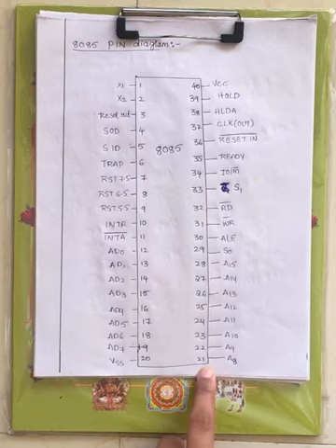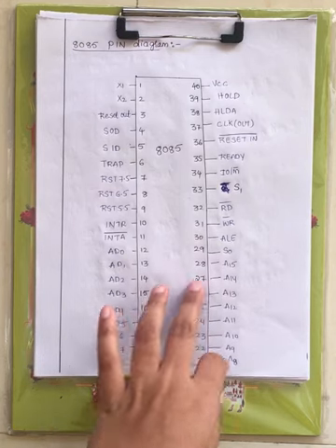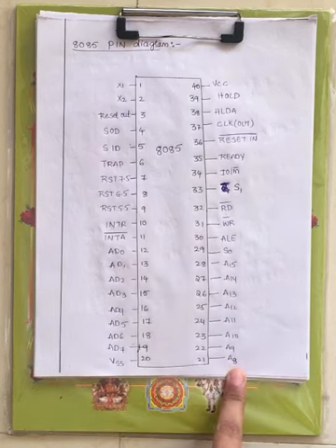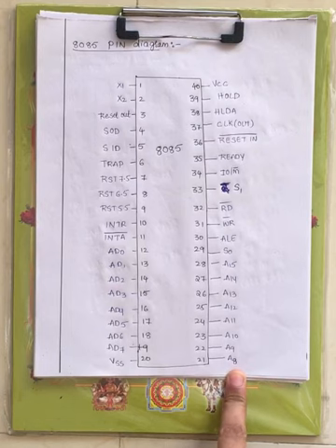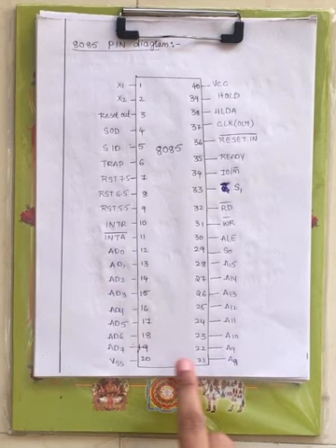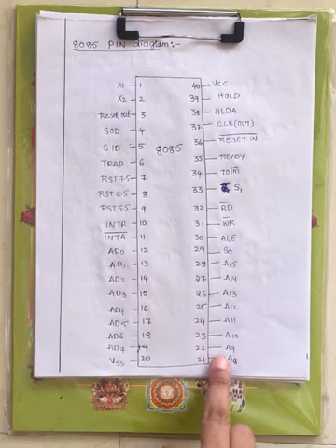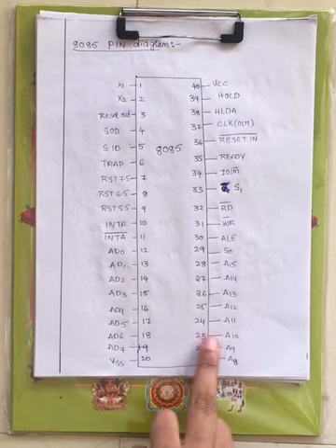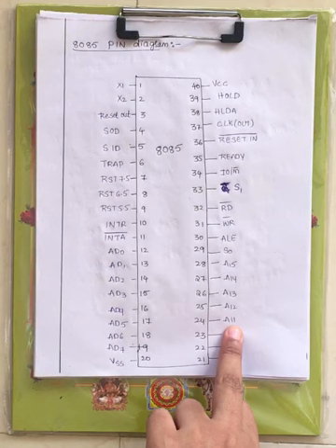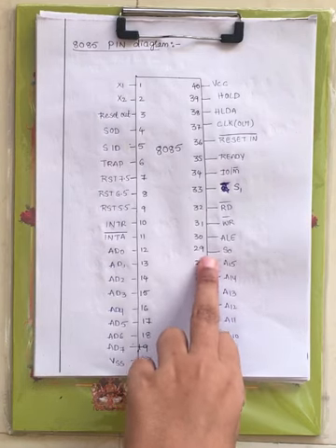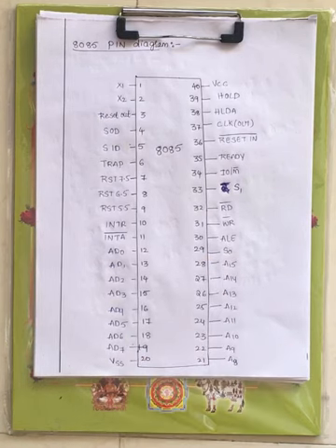Now 21 to 28. At 21 you have address bit 8, A8, that is the 9th, counting starting from 0. At 22 you have A9, at 23 A10, at the 24th pin you have A11, and so on. This will vary up to 28.